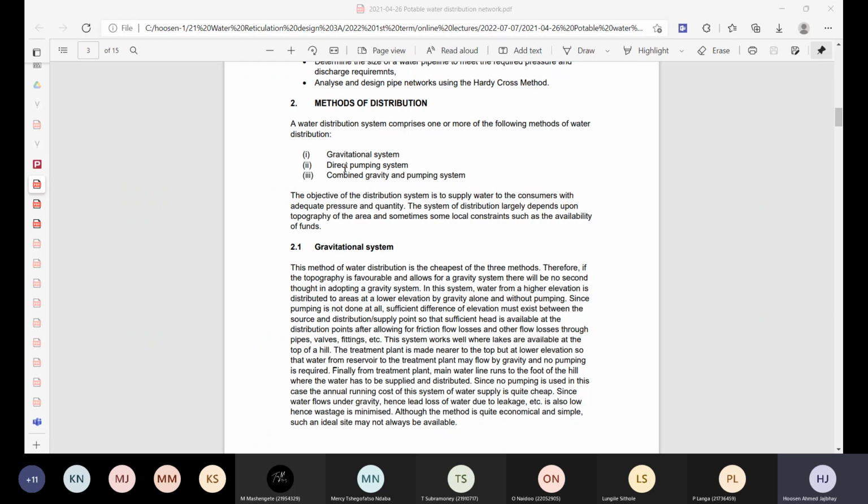It is also very expensive. The pumps use electricity, they need electrical energy. The pumps themselves require maintenance from time to time. They need downtime, they need to be serviced, and the pumps themselves are very expensive. So as far as possible, we would generally avoid a direct pumping system, or try to avoid the use of pumps in total if we can.